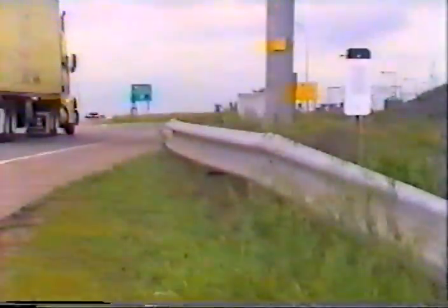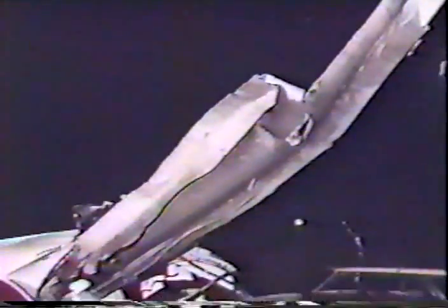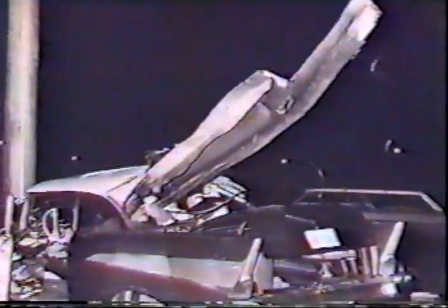The more rigid the system, the more rigid the post must be. It is crucial to design the right size posts and to use the right kind of material. Once the right material is determined, that material is used on all the posts. You don't mix types of post material. The bolts connecting the plate beams also provide strength to the whole system. The end on a plate beam system is twisted or bent down in order to prevent serious injury to the passengers in the car. If left out, the end piece could easily pierce the vehicle and impale the passengers in the process.